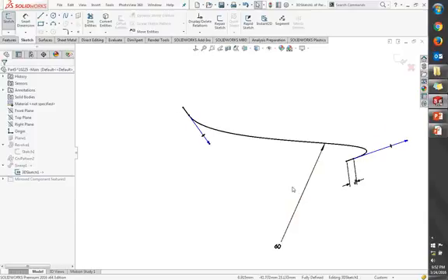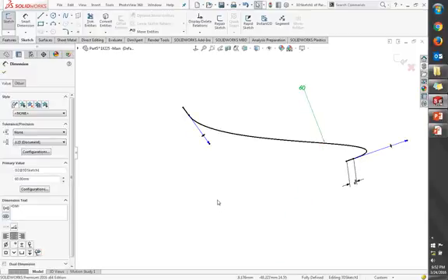So at the assembly level, I inserted a virtual component, and then I created this three-dimensional spline, made sure I had relationships to control the tangencies. One of the things you can do with splines, even though it's not an assembly thing, is put a dimension on the spline, and no matter what you do to it, it has to stay that length. That works out pretty good because it's a fixed length that I have to work with.